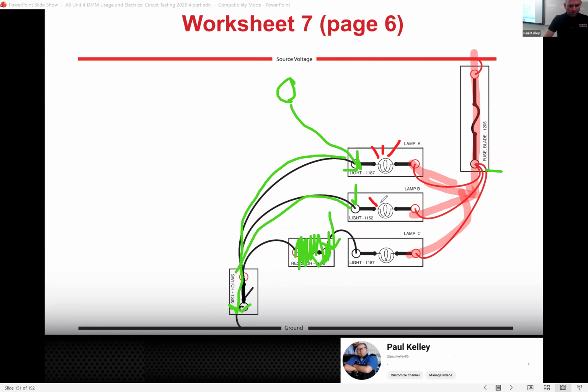A bright bulb, 1, 2, 3. And then with this one, you'd have a dim bulb, 1, 1.5. You'd have a dim bulb. Why would you have a dim bulb? Yeah, it's got too much resistance in this part of the circuit. This resistor has no effect on this, has no effect on this. It only affects this part of the circuit, and that's why we diagnose it as like a little mini series circuit.